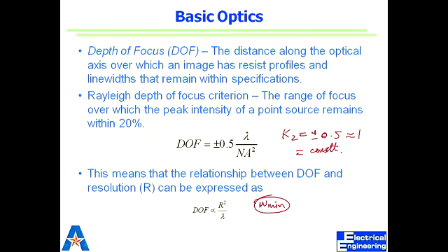So another factor is depth of focus. We have probably discussed this a little bit. Depth of focus is the tolerable distance within which we can get the image registered and the energy transfer to occur. In layman's language, it's having different planes in focus. With multiple layers and different heights of features, we want the depth of focus to be large. But what we see is if you push lambda down to get smaller feature size, the depth of focus is also compromised, right?